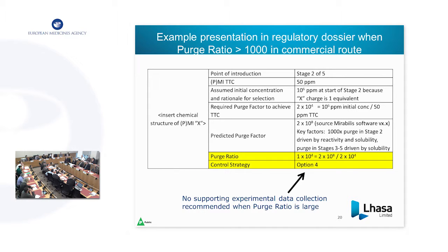And just building very quickly on that, as many of you will be aware, we've had the incident recently with valsartan, the contamination with nitrosamines. We have a drug ourselves which is a sartan, candesartan. And as soon as the issue hit, we tried to work out how it could have been formed and what the reagents involved were. One of the first things we did was a purge calculation to determine whether we could have any actual risk. Within half an hour, we calculated that for our manufacturing process there was no risk of generating NDMA.